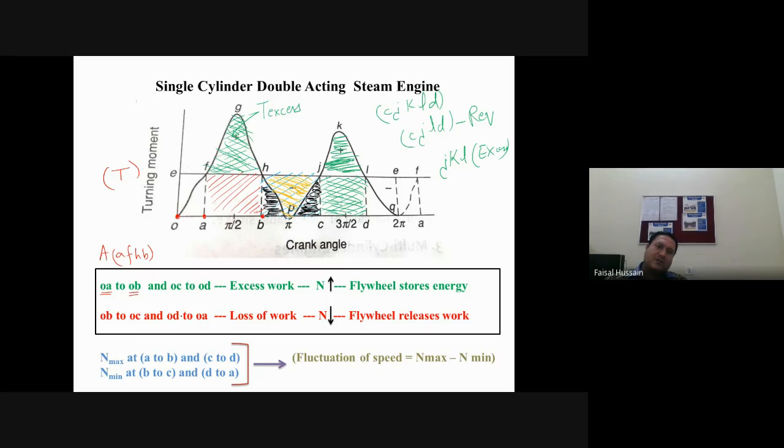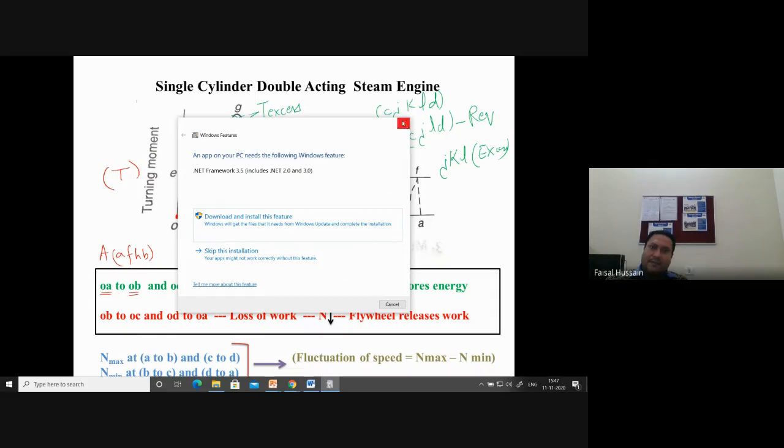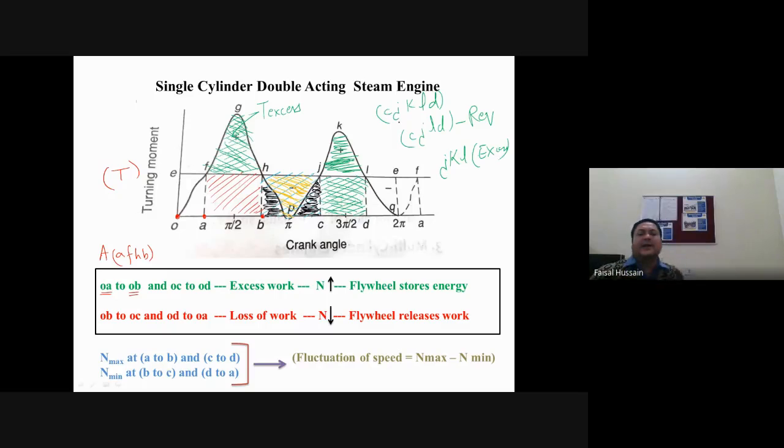For your understanding, see, during the first outward stroke, AFGHB is the total area. We need AFHB. So FGH is the excess energy which is stored. Then BHGC is the total requirement, but only HPJ is available. So here we have to complete the HBP and JCP work done requirement. This is taken from the excess energy. So this process is followed.